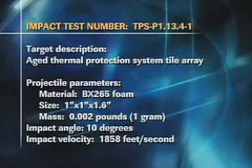We're going to impact this target at an impact angle of about 10 degrees, and 10 degrees and less is probably more typical of the sort of impacts that could occur on the vehicle, with an impact velocity of almost 1,900 feet per second. So roll the video. A side view of the impact. This will roll a couple of times. The foam leaves the barrel of the gun. You see on the left-hand side, this is the tile target. You see some material coming up off the surface there. The foam strikes the target and some coating is removed from the surface.